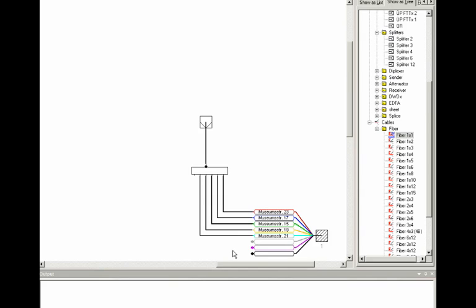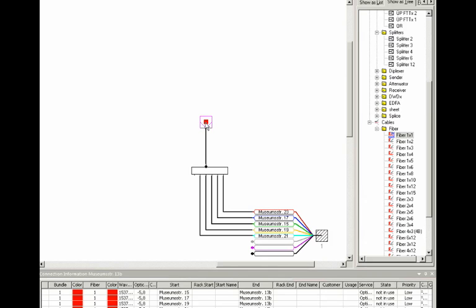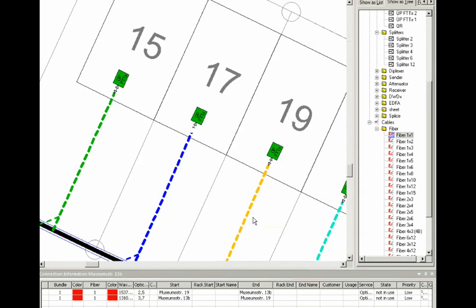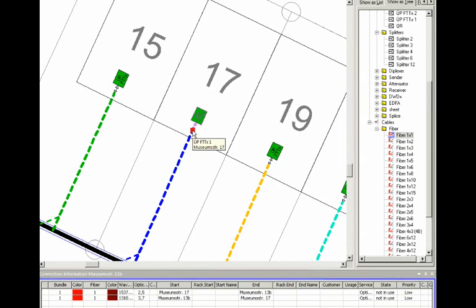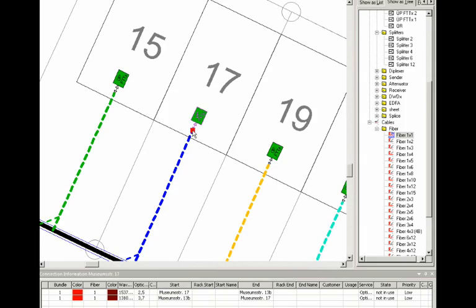So to see now the signal itself, just move the mouse on the exit pin of the signal source and press R. In the lower part of the screen you see the result. Do the same for the exit of a splitter and you see the signal. Now if we move with the mouse on the expander and press the W key, it will jump to the termination device. You can see the blinking pin, and if we press R there, we can see the calculation result of the optical power down there.